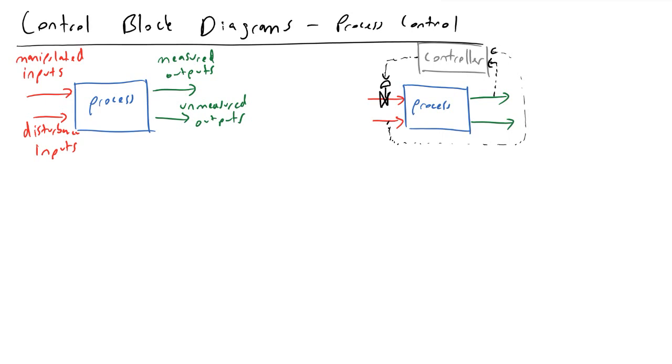So what I mean by that is, if we knew that there was going to be a surge in water coming into our system, and we knew that things were about to become diluted, our controller could have some logic in place to help adjust the flow rate of some feed in our system to account for that before it actually makes a change to our output in our system. And so those are for more complex processes. And so generally, when you begin a process control class, we're going to stick mostly with feedback control, but you will discuss feed-forward control later on.